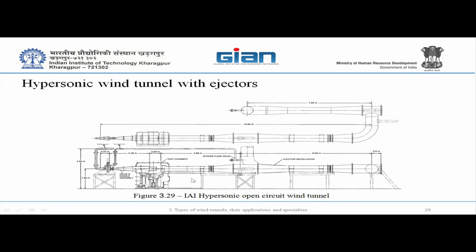I think I have photos. I have some plots of this later on. I have some of the profiles. So this pipe is coming from the heater. After dryer, filter, heater, it comes here. When you start to run, the main flow goes through the heater, but the valve sends the flow on the third branch out to the muffler until the temperature is stable. Once it's stable, the valve is opened and the main flow goes through the mainstream.